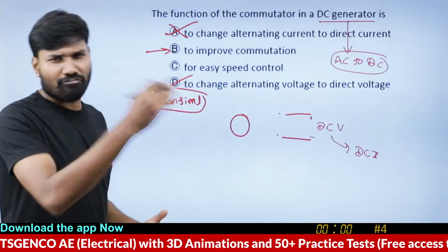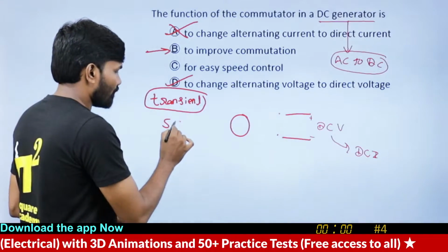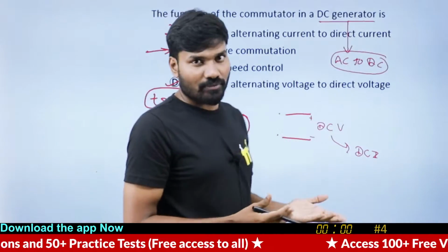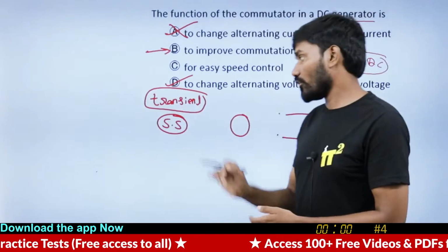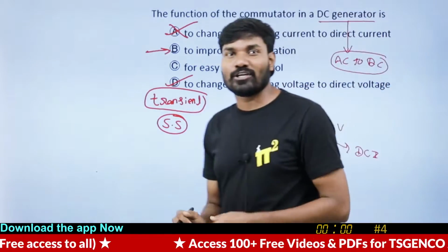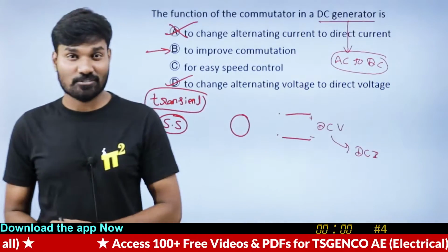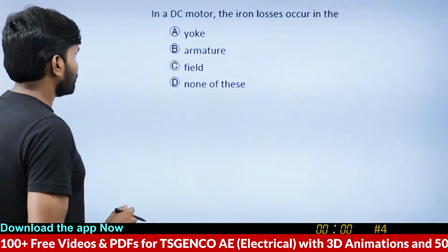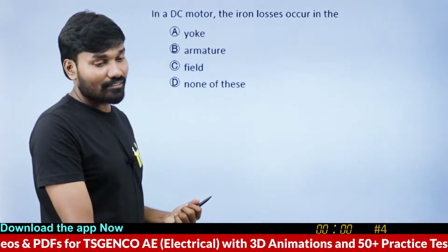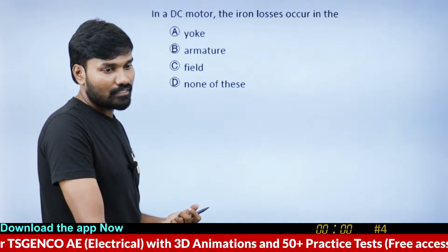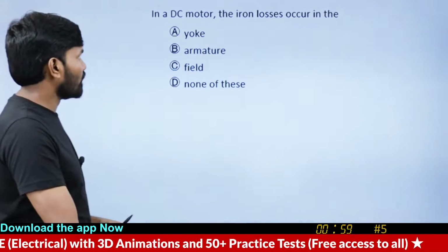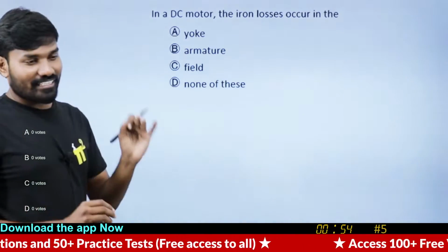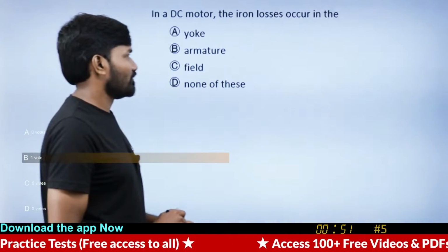Now the analysis you are doing is all steady state analysis. At steady state, there is no effect of an inductor for a DC supply. But during dynamics or transient, you have to include the inductance as well. Good point, by the way. That's what you have to see, what you're dealing with. You're dealing with the steady state, that's why you don't normally study that effect. This is an easy one, but there is something interesting analysis behind this as well. Let's see this.